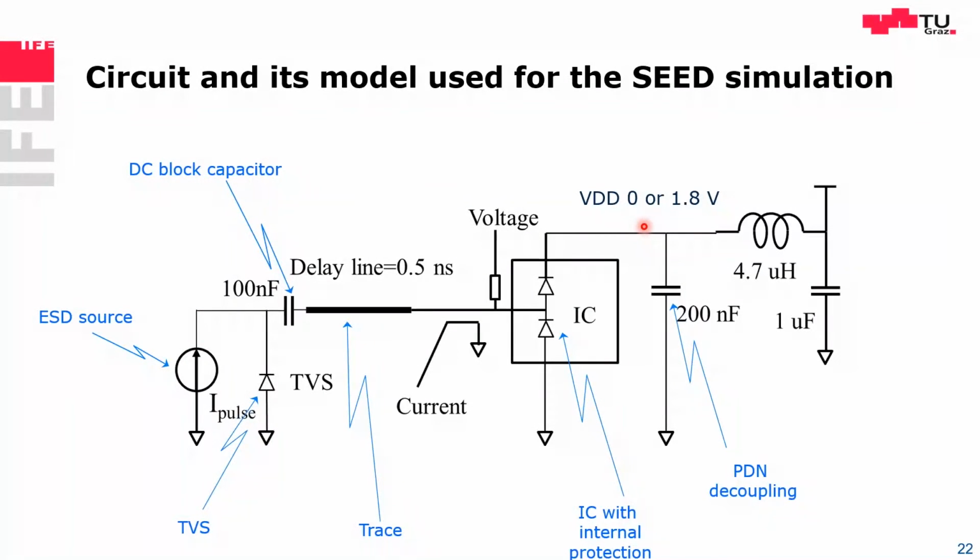Now let's use a model. Let's take a usage example. This is the structure we have. Let's say here's an IC, and every IC has an ESD protection. And let's say this IC has a dual diode protection. It has a big capacitor on the outside, 200 nano. It's like a short for ESD. And here we just have some decoupler and get some power.